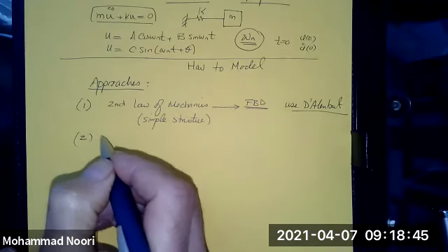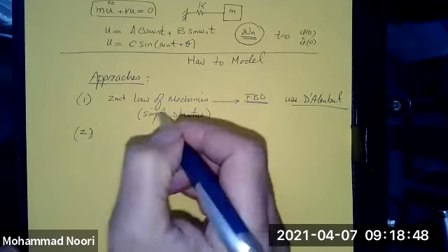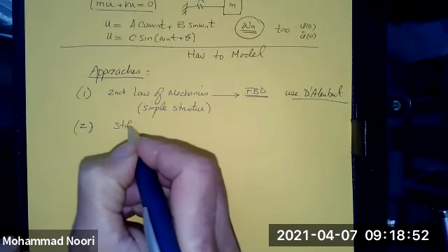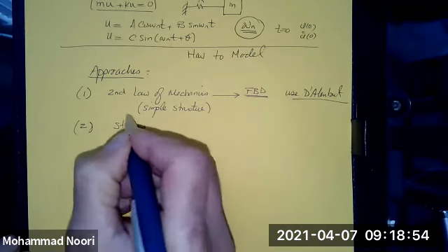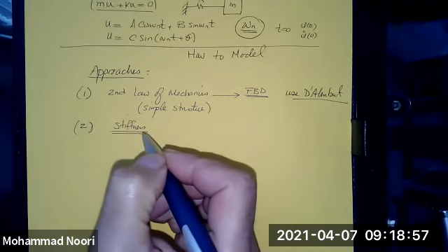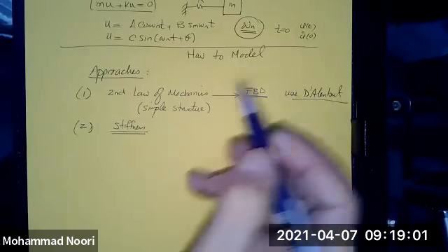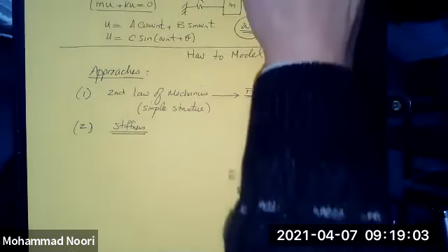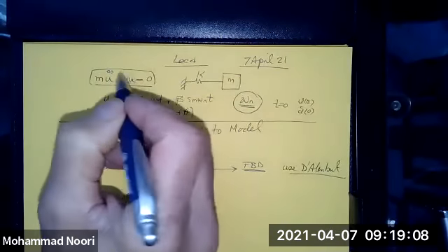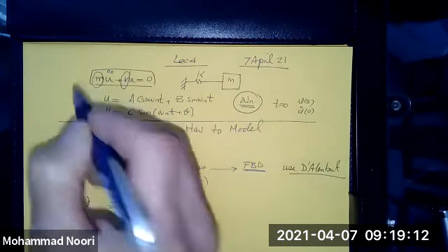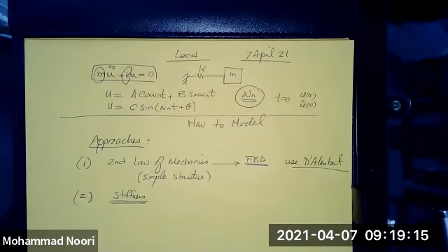If the problem is a little bit more complicated, or actually as part of that approach, you see that it is sometimes easier to simply try to find the stiffness component. You see in this formulation, in this modeling, the most important part is to define K, because the mass is relatively easy, almost identifiable in most cases.